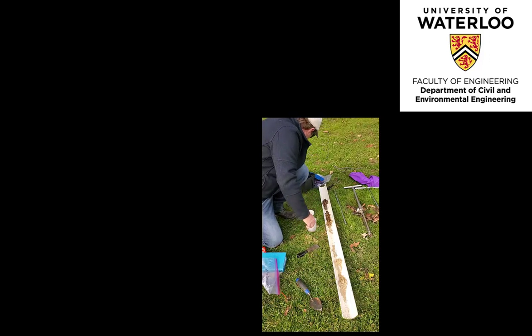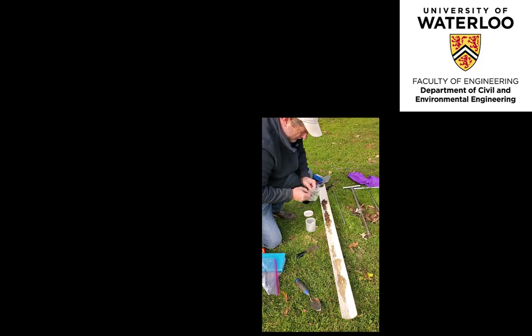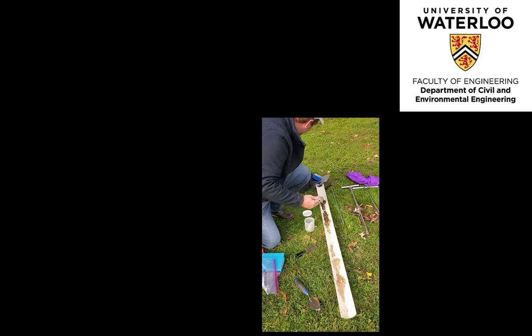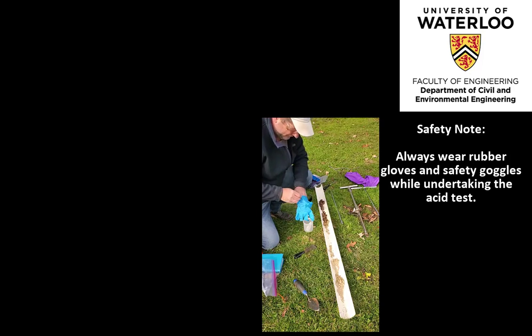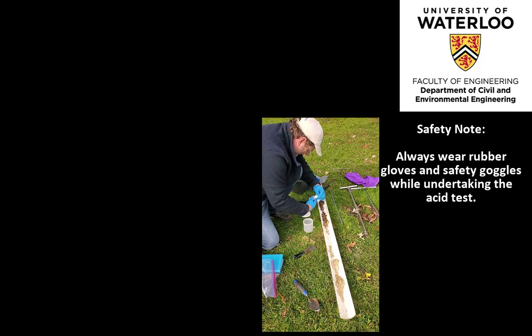Lastly, an acid test was undertaken on the E horizon to test for the presence of carbonates. Here, drops of 10% hydrochloric acid are dispensed onto the sample and the degree of effervescence or bubbling observed and interpreted. It is important to investigate the presence of carbonates in an infiltration study, as dissolution of carbonates may occur at the ground surface due to reactions with the atmospheric carbon dioxide, but may create a pan layer at some distance below the ground surface which would impede or could impede infiltration into the subsurface.